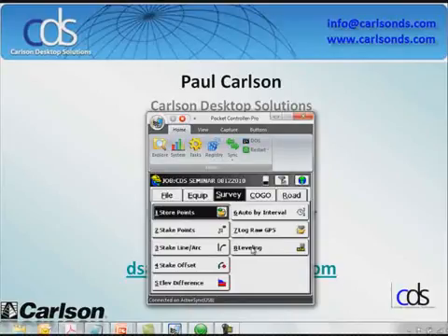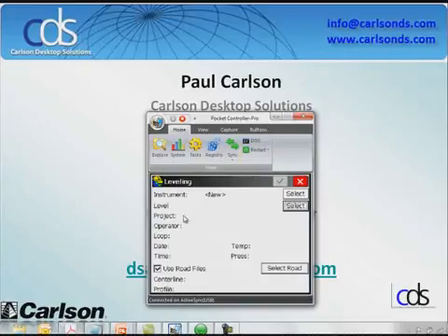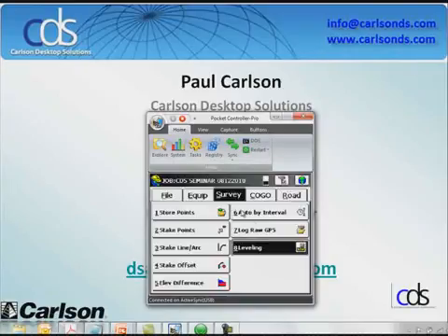There is the instrument level. I don't know if I have that option on here, but like with my total stations, I can go in and make sure that if my instrument has a dual axis compensator, has the level bubble digitally, I could see that. Log raw GPS, some receivers have the ability to log static. For example, the receiver I'm using has the ability to log the static data into the receiver itself, and that would be my status.